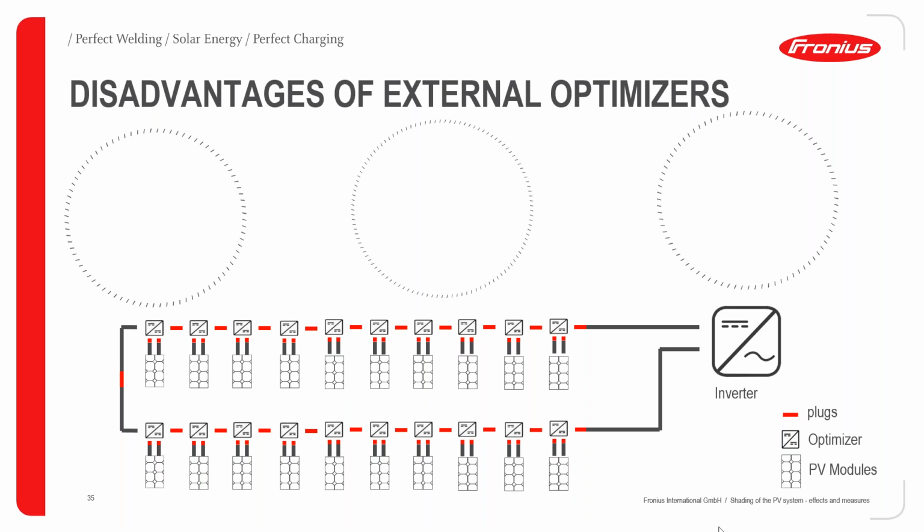Number one, because of the added components, there is less yield for your system at low to moderate shading, because as you know, the DC optimizers themselves are electronic components, and because of the resistance and this kind of thing, measurements for operations, the DC optimizers are consuming a bit of energy that is produced by your PV array, and therefore that, to start with, results in lower yield from your system.